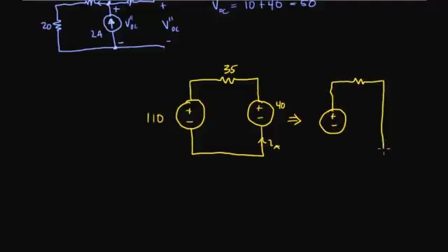And you'll get that if you just do KVL around the loop, right? 35, and we're looking for this, IA. Well, just by this battery here, this voltage source, I can tell that the current flowing through this circuit has got to be in this direction. So IA is going to be the negative of whatever value we get.